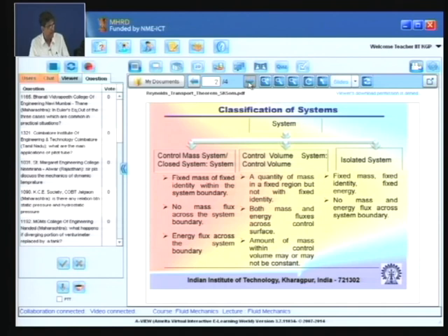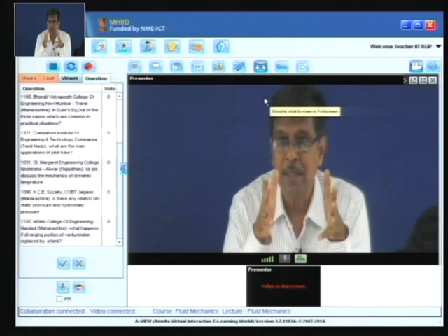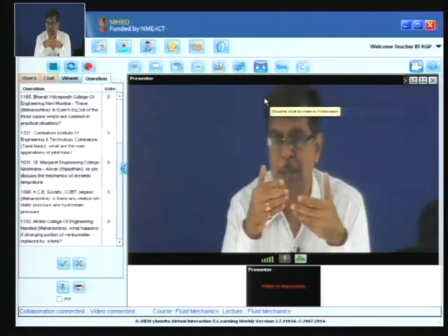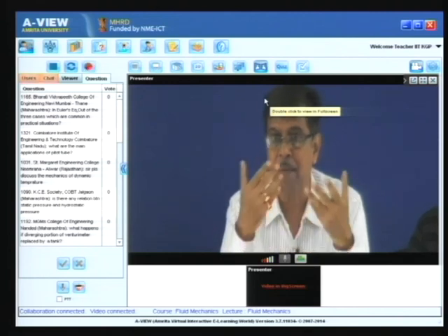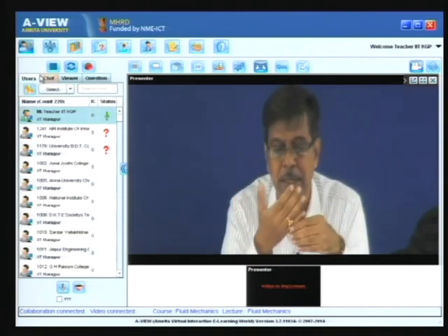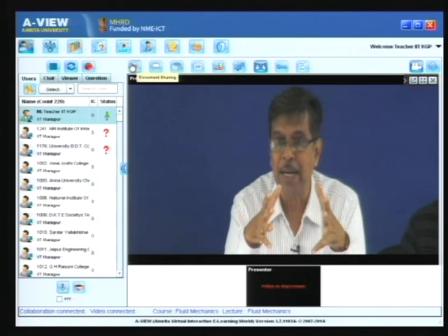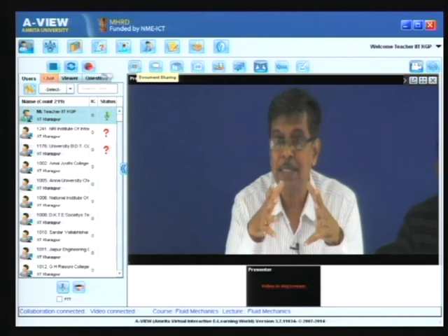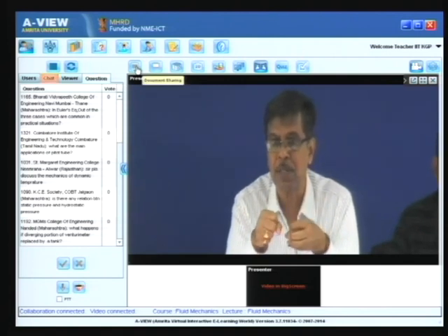Now, next I will tell you one very important thing. What is Reynolds transport theorem? Now, let me tell you like this. Basic laws of physics relating to conservation of mass, conservation of energy, conservation of momentum, all these basic conservation laws or any other laws of physics, for example, the first law, which is nothing but the conservation of energy, first law of thermodynamics, are all basically defined with respect to a system, meaning a control mass system. For example, we always say for conservation of mass, the mass of a system is constant, is conserved.